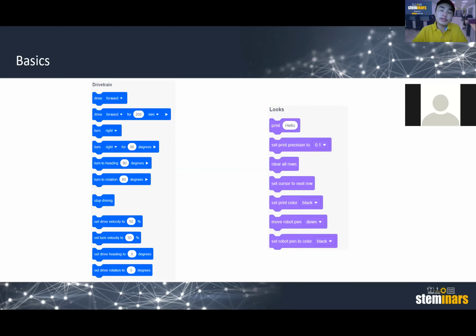What a gyro sensor does is, at the very beginning when you start up your program, it will register that point as 0, 0. Say if you go forward for 200 millimeters, your gyro sensor is going to change. If you go forward, it's probably going to be in the Y direction. So after going forward 200 millimeters, your coordinates are going to turn into 0, 200. It's complicated, I know, but when you go into practice, you'll understand it way easier.